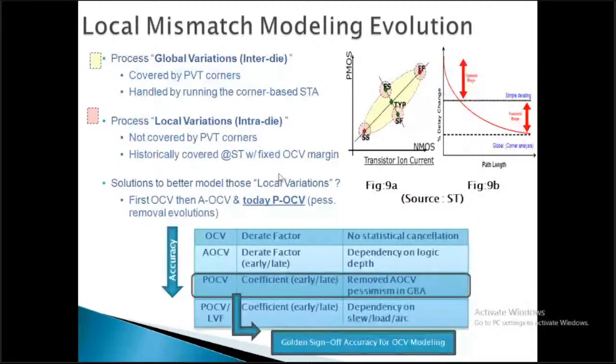So again, if it starts to collide, current will start to fall, and current falling means our circuit will get more delay. So with increasing temperature, sometimes our circuit becomes fast. Again, with increasing temperature further, it becomes slow. So we have to take care of all the factors of the circuit.